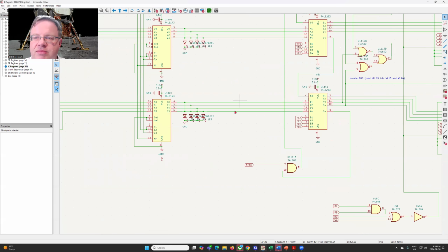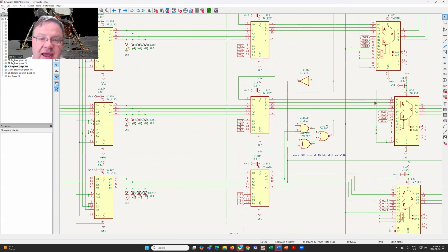The reason I did that is that we have the adders, and then we have the ALUs to do the logical ORing for the write buses, plus a bunch of control logic, both on the input and output side. The X register, from a circuit board perspective, starts getting fairly complicated. Now, I did just receive my second set of boards that I'm using to build the computer on, and I made the second set larger. With the originals I could put up to 25 chips onto a single board; the new ones can take 35 chips, so they're a little bit longer. So I can fit some of the more complex boards like the X register, and as we get into the G register, which is also quite complex, and then the S register as well, we'll have plenty of space on those boards to build them out.